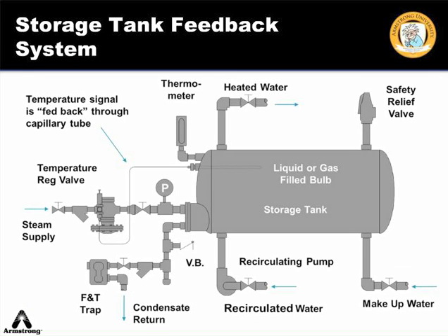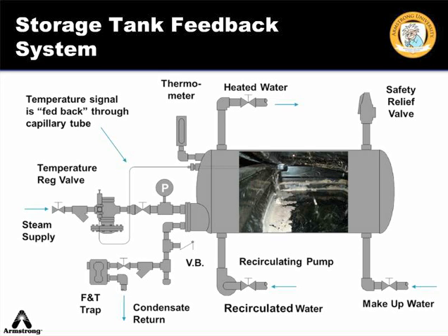This is a typical storage tank feedback unit used in some institutional hot water systems. As water is circulated through the system and through the water heater, colder water is along the bottom of the tank around a heating bundle. It becomes a common bacterial amplifier for Legionella because of the temperature stratification that can occur within the tank. Scale that builds up on the heat exchanger over time falls off and collects in the bottom of the tank, creating a stagnant area where the water cannot be recirculated.